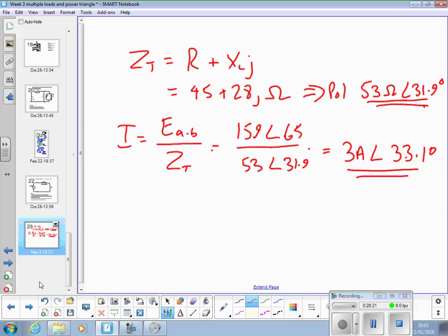We go round anti-clockwise, so the voltage is ahead. Is that right for an inductive circuit? Yes. Okay, but it's always worthwhile just thinking, does that make sense? And that's a bit more tricky when one of the angles isn't zero, you need to think about where it is. Yeah. Alright? Always worthwhile looking at that.